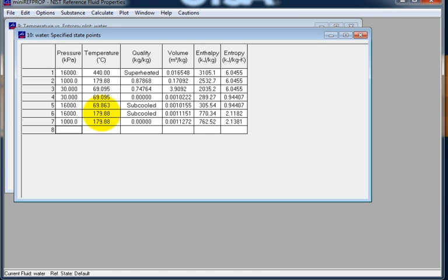That's after the steam trap. What is the pressure at state 8? It's after the steam trap. The steam trap drops the pressure. Look at the symbol of the steam trap. It's like a valve with a circle on it. It's 30 because it dumps into the condenser at 30. So it's 30 kilopascal. But what's the second property?